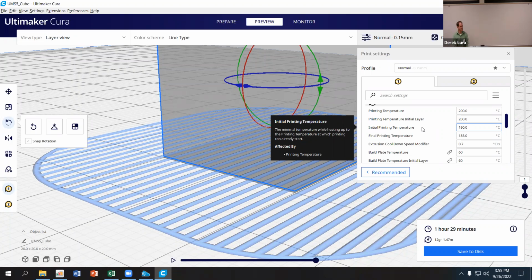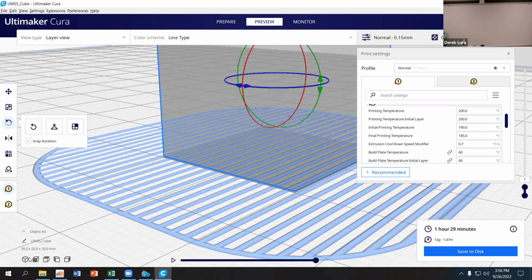If I have a part like this, this is just a spreader bar. This is actually the spreader bar we used last year for applying loads. This is pretty strong because all the fibers, really the print layers, are going in the same direction. And so when I bend it, the forces on the top and the bottom are in tension and compression. And the forces going in this direction, right, are very, very small. So the parts when they come out of the printer are typically very anisotropic. Their strength characteristics are very much a function of the direction of the print.